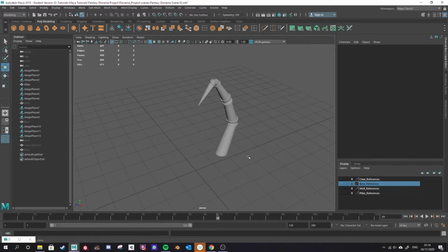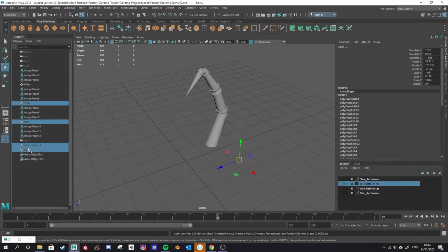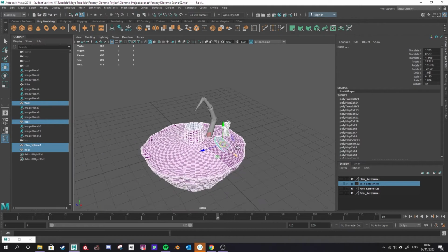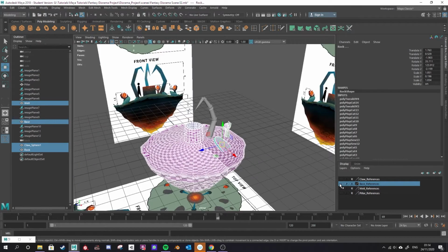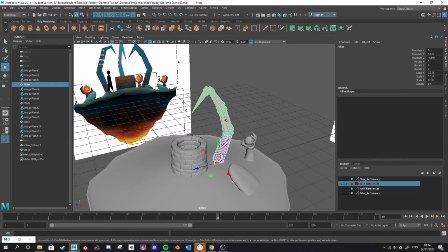Now, just as I'm moving on to this, one important point to note is I have a bunch of objects here that I'm going to be creating. You'll see from my reference that I have 3 of these claws, I have 3 of these pillars, and I have several of these stones. Now, a very important workflow tip: if I duplicated, say, this pillar before I UV unwrapped it, what I would need to do is unwrap each one of the duplicate pillars individually. So you're creating 3 times as much work for yourself. Anywhere where you have duplicate geometry, keep 1 copy only.